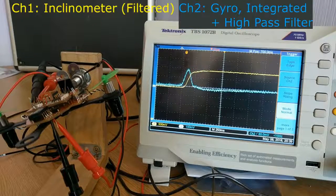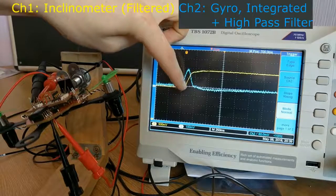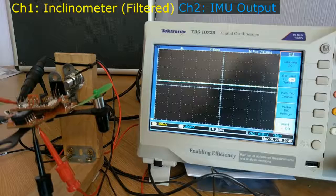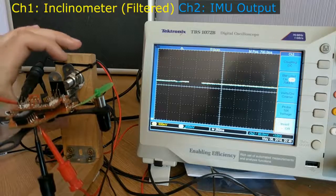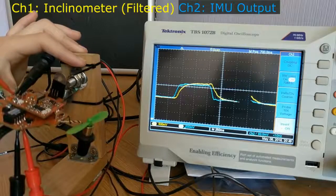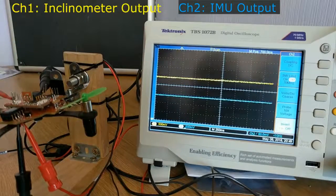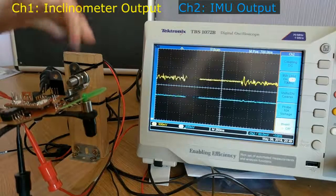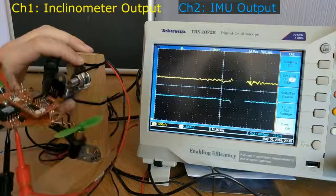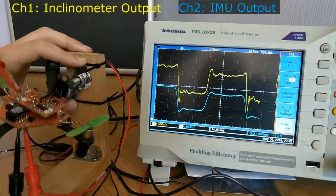The pulse then decays at the same rate that the inclinometer pulse edge rises. The gyroscope pulse and slow responding inclinometer signal can be summed together, and this gives back the fast responding pulses. This new signal is resistant to vibration. The inclinometer shown at the top vibrates while the bottom signal doesn't, but it also responds quickly to a roll.